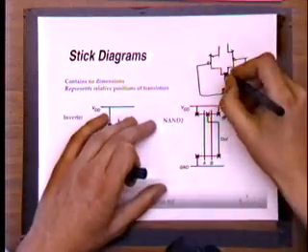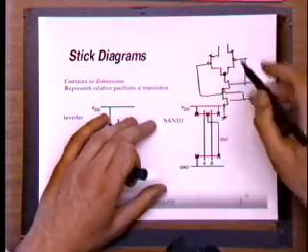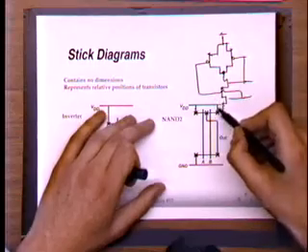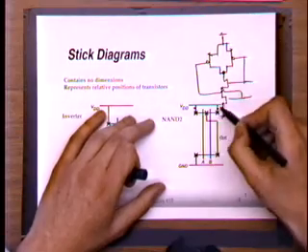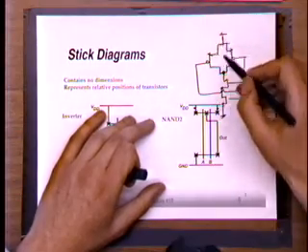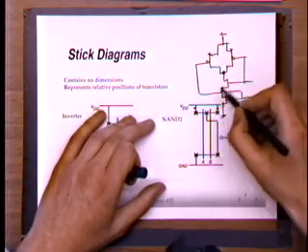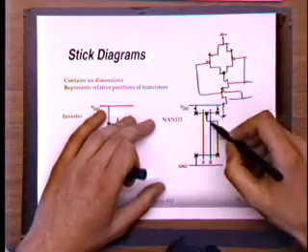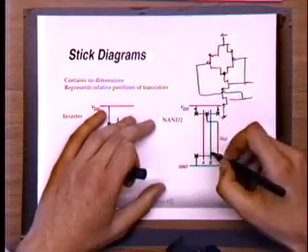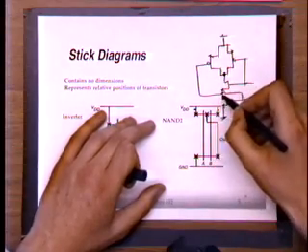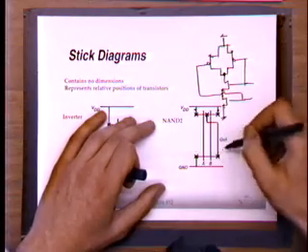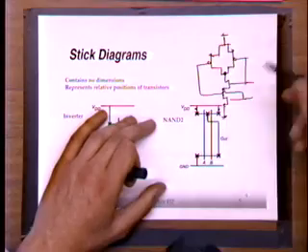And so you can imagine this node, this common drain. So there is the sources of the PMOS 1 and 2 are tied to VDD, and here are the sources. And the common drain of the PMOS, it's here. It's tied to the drain of the first NMOS. And then you can see that there is no contact for the junction of these. So these NMOS are really laid out as a multi-finger transistor. I'll get back to this in the next slide.